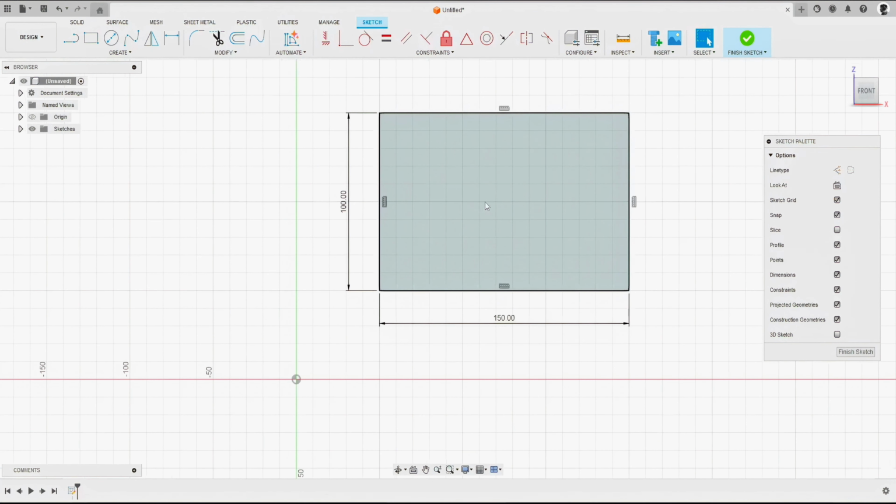For example, under equal distance chamfer, we can see there that the chamfer in this case is 20 by 20, so 20 mil vertical, 20 mil horizontal. We've got the distance and angle. So that's where we put a distance on either, in this case, the horizontal, or we can do the vertical, and then the angle would be applied, and that would determine the distance on the opposite, whether it's the horizontal or vertical. And then we've got the 2 distance chamfer. So this is where we have essentially a non-equal distance chamfer.